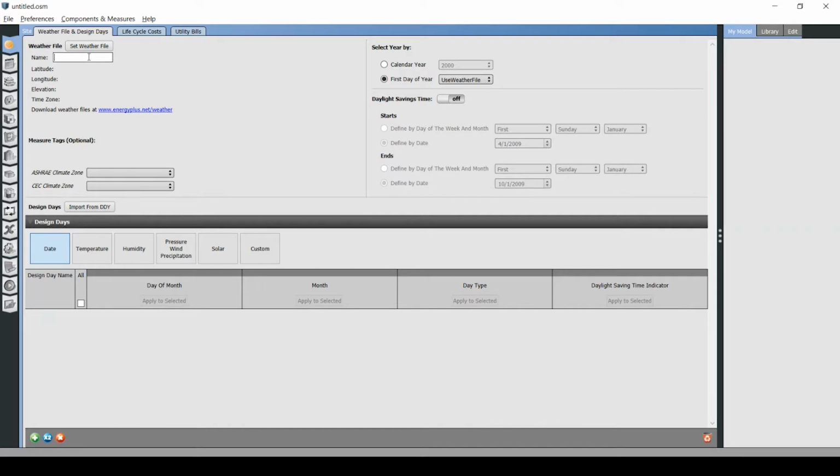After running the measure, we will use the OpenStudio application to inspect and modify some of the input parameters of the model, which will allow us to visually see the changes that we will make to the model. We will then execute the energy model, which will be an annual simulation of the building, and we will review the results. Reviewing these results will ensure that our model ran as expected.